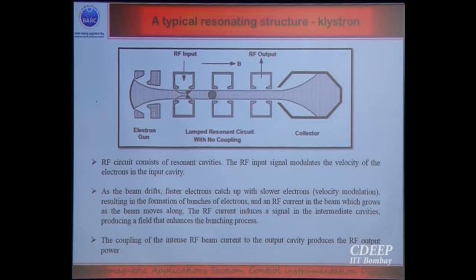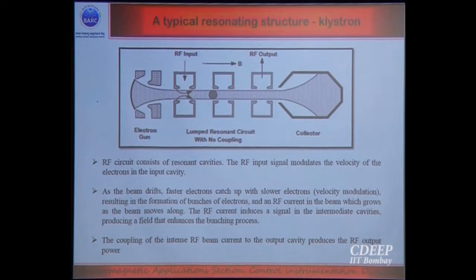First we derive electron beams from the cathode gun. Then once it enters the cavities, in simple terms, I explain a 3 cavity system. In various applications there are 5 cavities or 4 cavities in klystrons to increase the gain. In the first cavity, as the beam enters, if we take a simple sinusoid, this is an RF cycle.